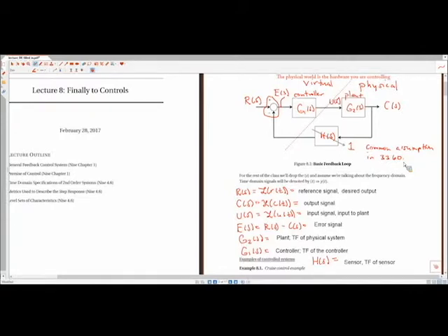So the if-else would all live in G1 in a computer. Right? Assuming that you're talking about computer logic, right? So it would look the same, if all these if-else's are like if this, do this control action. It would look the same as this as long as you're working on the error signal. So here we're assuming that all your if-else conditions would be on the signal E of S. If they're on something else, then it wouldn't look like this.